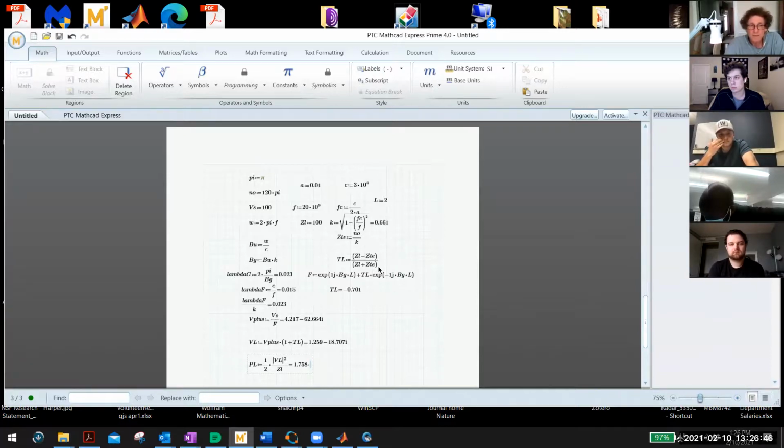Isn't it this right here? You want to make the reflection coefficient 0, don't you? So if the load impedance is the characteristic impedance at that frequency, then you've got a reflection coefficient of 0. Then all the transmitted power is dissipated, none's reflected. That's the idea. Another thing you've got to remember, especially with high power things like radar antennas that you're feeding, you never want any significant reflection coefficient because that power comes back at you. It can blow up a power amplifier or something. Remember that.